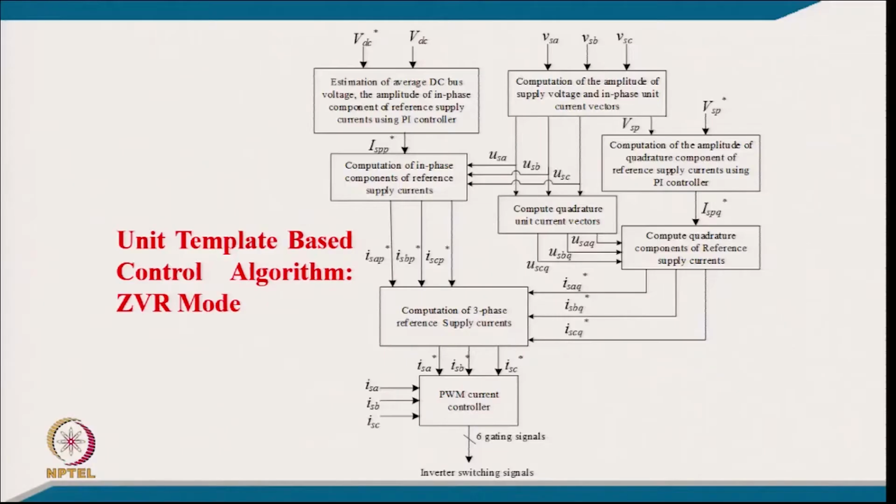Also, sometimes we use a sliding mode controller, which does not have overshoot or undershoot, but that may have a 1 or 2% steady state error, but certainly you will not damage the devices in that case. So, that is about the first control algorithm for power factor correction.